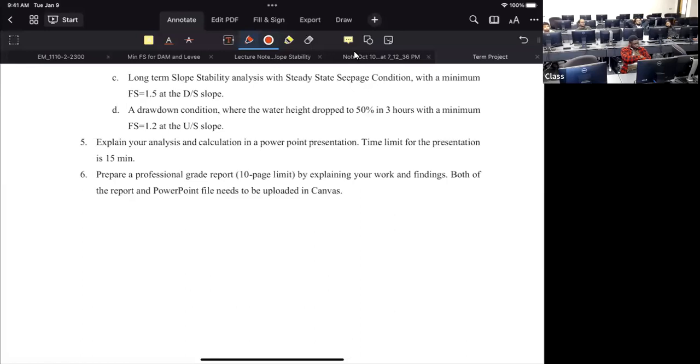Now, do you know how flood control is done in the US? How can flood control be conducted? How does flooding work? You have a discharge and you have control, a loss of volume, right? If you cut off some flow, your major problem is you have a very high peak flow condition for a long period of time. So the best idea is you just cut off the peak flow, right? So cut off some flow from the system.